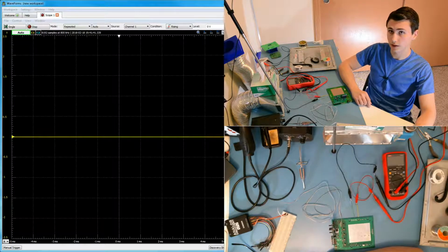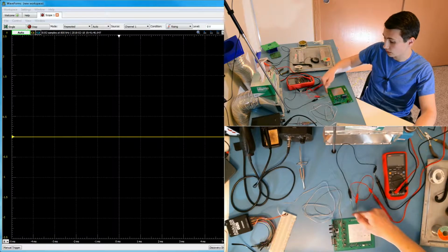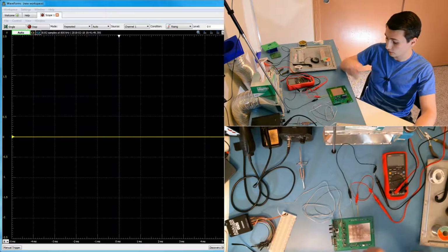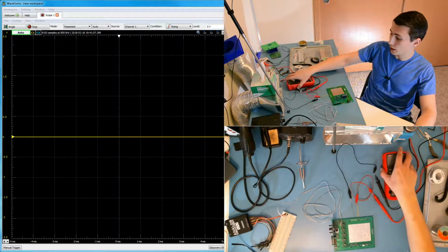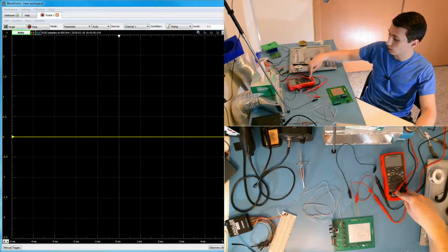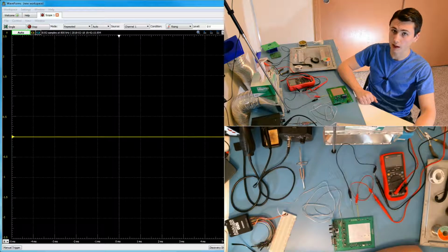So I have the workbench set up for us. I've soldered wires to each side of one of those current shunt resistors and to one side of each of the 0603 pads on the bottom of the blue channel. All of the other channels have been disabled, and then these two wires from the bottom come over to the multimeter, which is in current mode. The voltage will be measured by the Analog Discovery. I've been meaning to spring for a proper oscilloscope for a while, but frankly, I'm shocked at how well this pocket oscilloscope works, and I haven't really had an application that needs it yet.